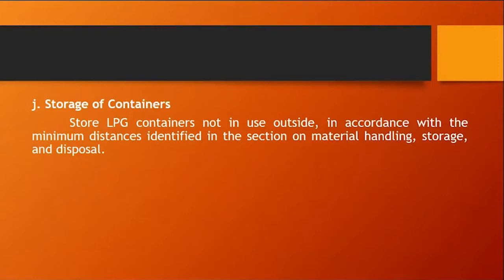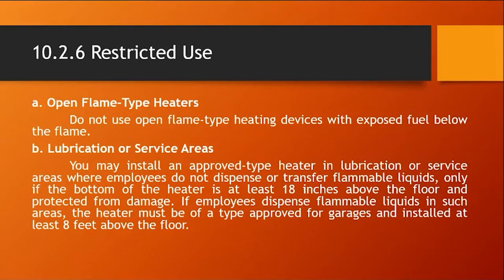Containers. Store LPG containers not in use outside in accordance with the minimum distances identified in the section on material handling, storage, and disposal. Material restricted use. For open flame type heaters, do not use open flame type heating devices. Next is for lubrication or service areas.